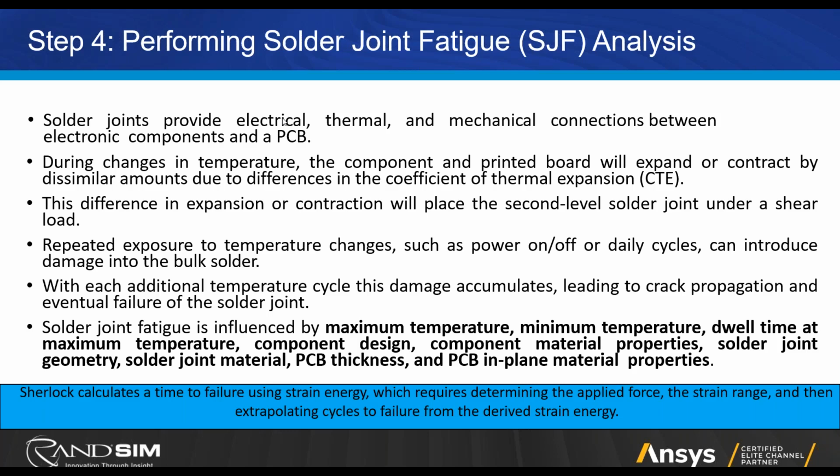And repeated thermal expansion can cause those little fractures to wedge farther and farther until you get something catastrophic like an open circuit. Many things impact solder joint fatigue.